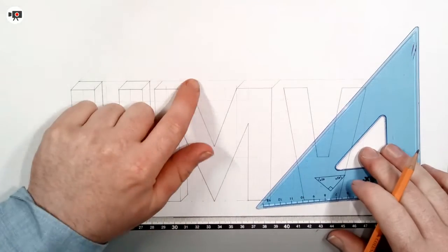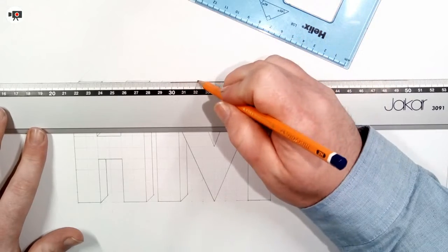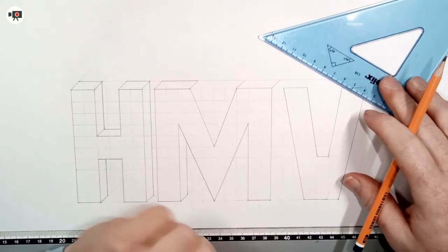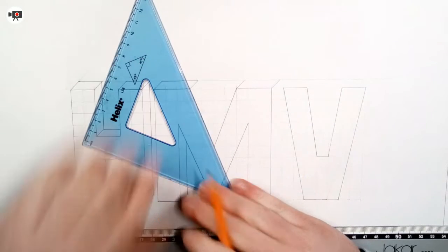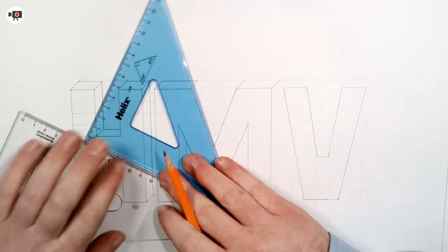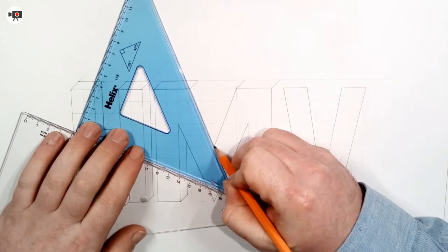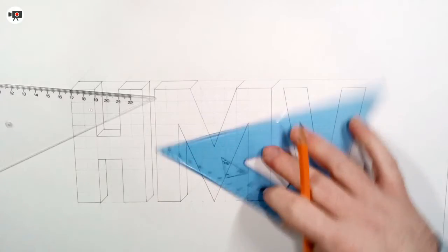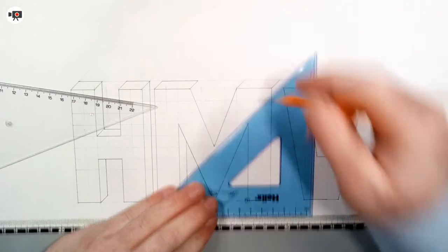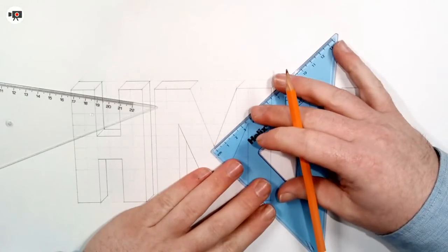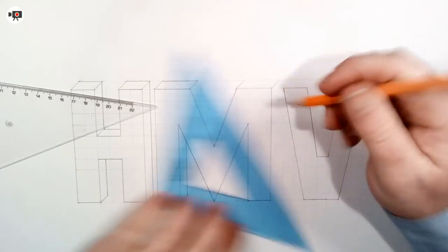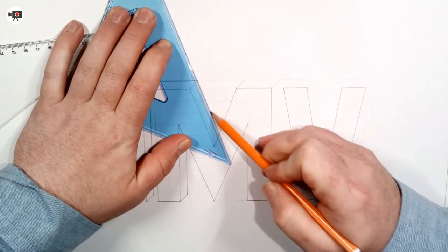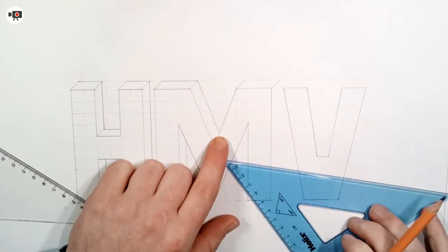I now need to find this inclined edge here. First off, I'll finish that line before I forget. To find this inclined edge here, you can do it two ways. One, you can go parallel using your sliding set squares, like this. Set up a set square and return it down parallel like that. Or you can, as normal, extend out at 45 degrees, measure your 10 millimeters, and then just join back. Stop where it meets the M there.